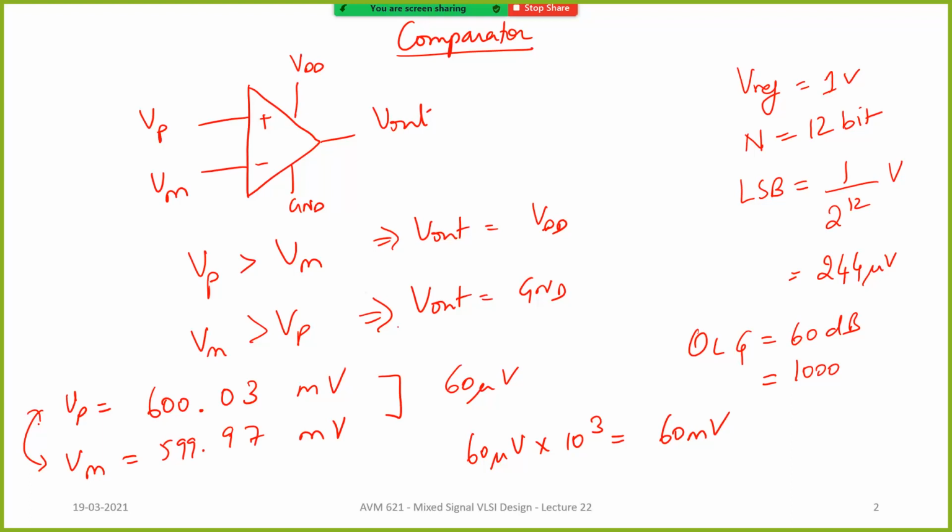So if you take 3 millivolt and give it to a PMOS connected to VDD, and the output is connected to that, it will be always on, always VDD, unless your input swing has become larger, right? So in other words, we require a very large amount of gain.